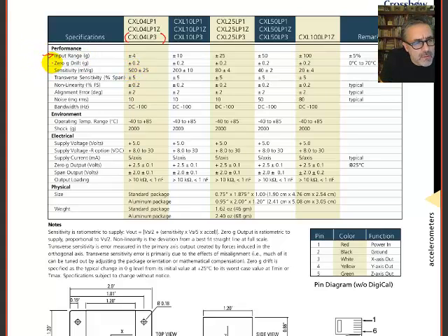There are other specs that are important. 0G drift means when you have no acceleration on there, what kind of change can you expect? That's a subtle one, but it's an important one. The sensitivity is, as with other sensors we've used in the lab, where we always measure calibration or sensitivity, the ratio, and this is a note, millivolts per G. Note that what it gives you is 500, or half a volt out, plus or minus 25 millivolts. So it's 0.5 volts per G output. You excite this by 1 G, you'll see it change by half a volt.